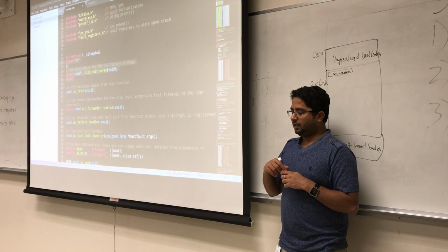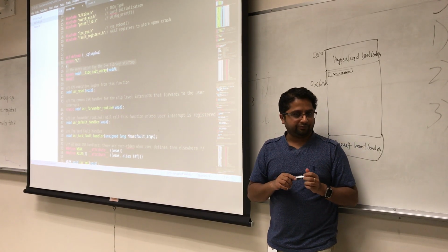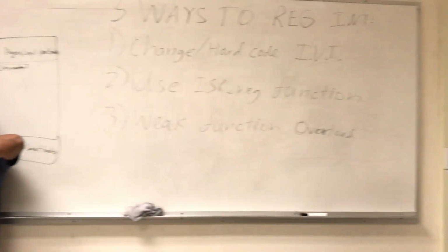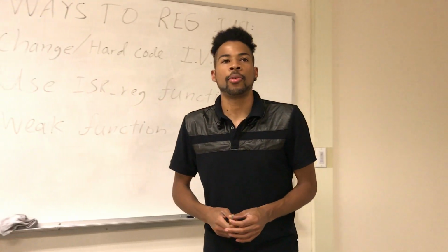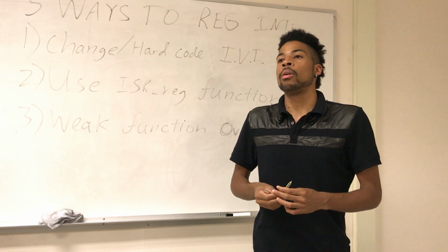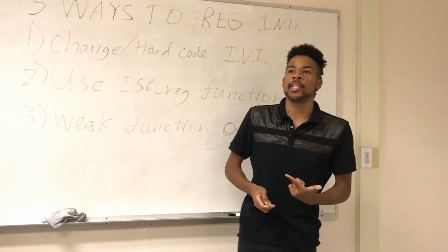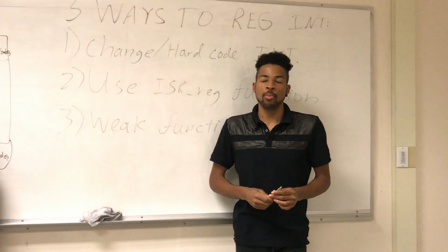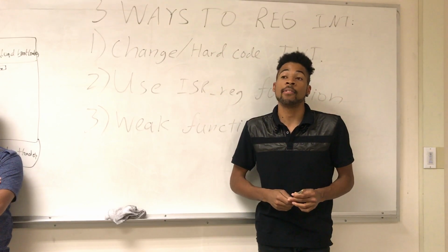So the way to do this lab is you will be considering one of the pins. Actually, hold on. Let me explain this part. For this lab, I don't want this to simply be where you set up a GPIO interrupt for one pin or two pins or whatever. I want you to be able to handle any and all pins on port 0 or port 2. The reason is that I want you to be a little more clever about how you design your firmware. Design a structure that can make your life a lot easier.